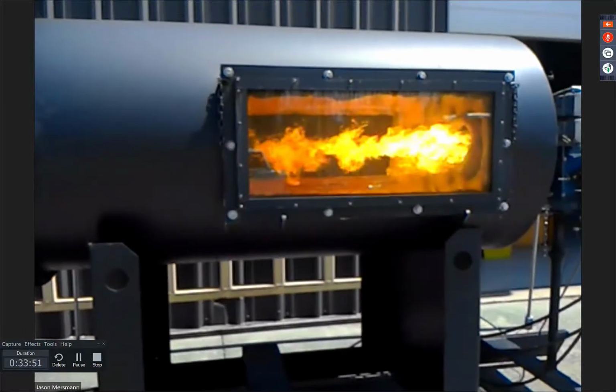You also saw that when it's incomplete, it started to starve the oxygen. When it started to starve the oxygen, you will see that the O2 percent starts to go very, very low, okay? And when that happens, like I said, the flame is starving. It wants more air, so it tends to be longer because it's looking for air.